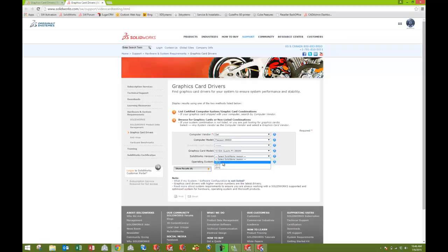But wait a minute, 2015 is not there. A lot of people are going to see this, especially in the next year. You know, every time new software comes out, you need to make sure you got the right specs running, if you start seeing problems, that is. But I immediately see what my case is. 2015 does not support the NVIDIA Quadro FX 2800. So I'm running the latest driver for SolidWorks 2014, and it's doing okay for now. Not to say that I won't run into issues, it just means that it's not supported by SolidWorks.